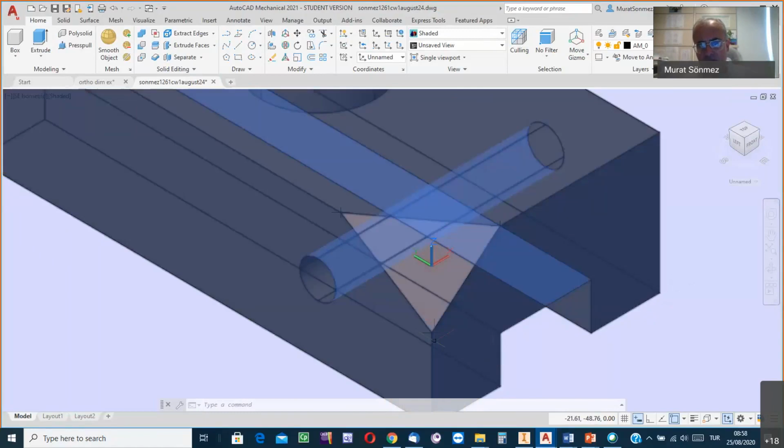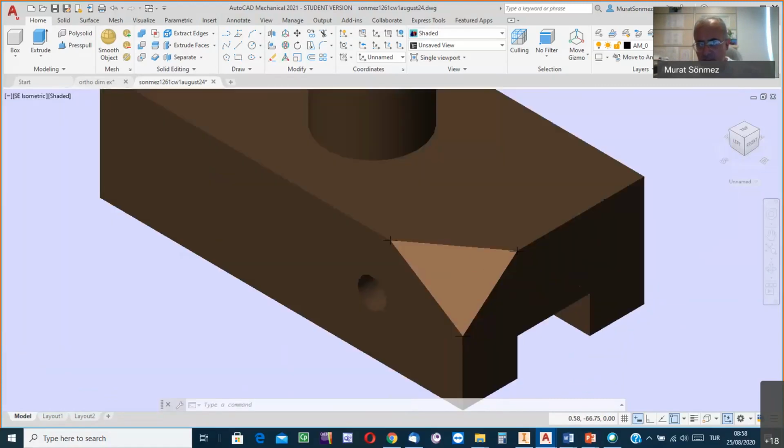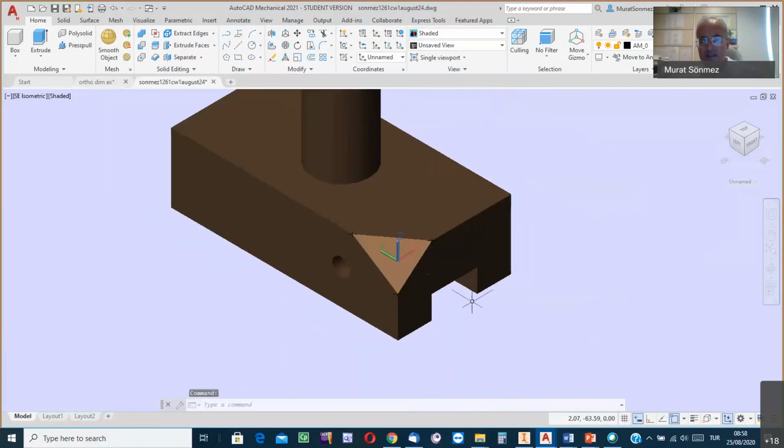For one of them, since the Z-axis is at the correct place, I clicked one more time on the comma button, comma key of the keyboard, then input the Z value as well for this point, I remember. Okay. Yes, I think it's okay. You remember the things studied yesterday, thanks to my brief reminding delivery.